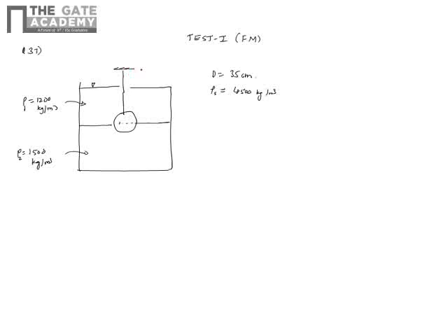Okay, so what do we do? Any kind of problem, we first draw a free body diagram of this sphere. Now weight is acting, mg. Tension is T, always pulling up the rope. Now half of this is in one fluid. Whenever you have a static fluid and something is immersed, whether it's partially or fully immersed, you have the upward thrust, which comes basically from Archimedes principle. The source is the fluid pressure. So this is the upward thrust F1 exerted by the top fluid. Then from the bottom fluid, you have F2, the upward thrust. So these are the forces acting on it.